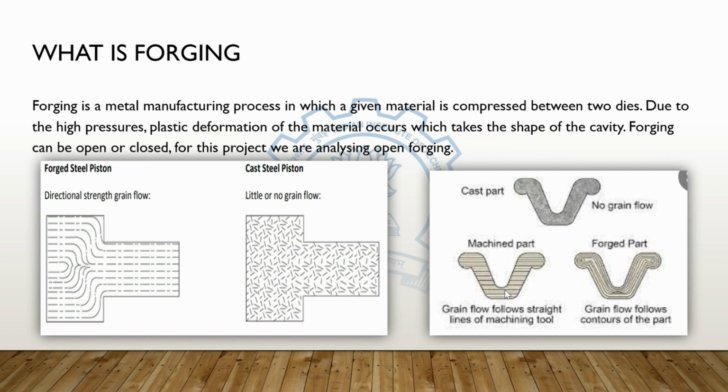The basic analysis is as done in the Ghosh and Mallik book, where the workpiece is compressed by the dies, and we have considered two regions, the sliding and the sticking region, in the geometry. We analyze the situation by taking an element from the one point end and one free end, and then applying the von Mises stress criterion to obtain the variation of stress generated in the workpiece. This is about the simple geometry, but here we have taken a hexagonal geometry that would be further done using numerical methods. It is very complicated to do it by hand and obtain an analytical solution.